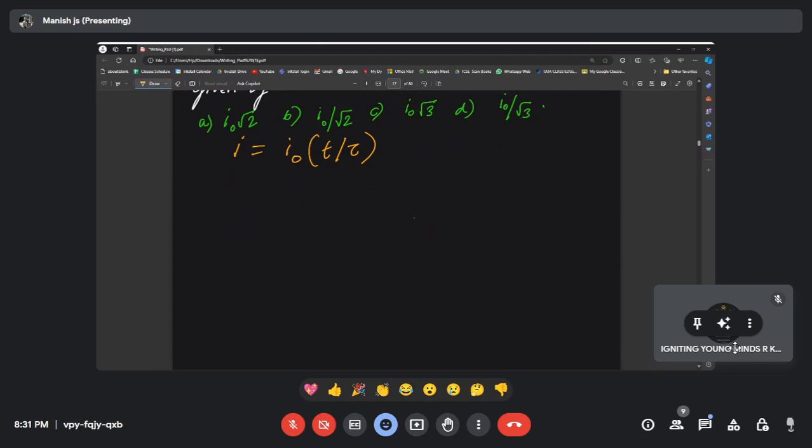Whenever we say root mean squared value or I RMS value, you need to understand that I RMS can be expressed as the square root of the mean of I whole squared. That squared value is what we want, a squared expression for a given function. First we want to find the mean value of I squared, so find that first. You have the expression here, so substitute.